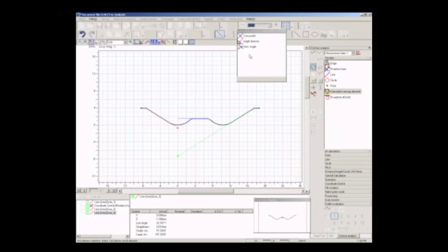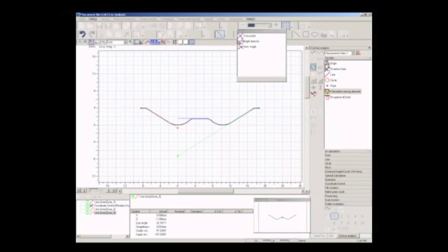Oh, okay, so this is pretty cool. Based on the features that you've selected, it knows there are only certain types of measurements that you can do. So that's all it shows the operator or the programmer. And the icon is also built to give you an illustration of what that feature is too. Okay. So it's more intuitive. But we're going to do an intersection angle, and as soon as we click on that, it measures that angle and drops a dimension in there right on our graph. And with this tool, I can move that around and put it wherever I need it to make room for other features I'm going to create.